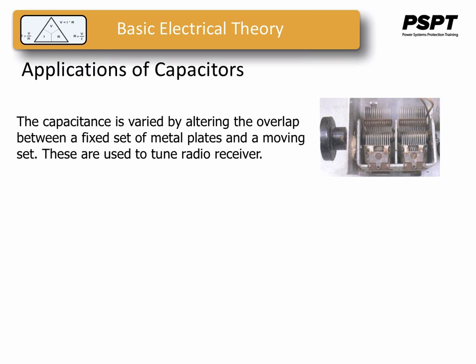They had meshing plates that varied the capacitance of the tuner, and these plates would actually move in close to each other and away from each other. So you'd vary the distance between the plates as well as the area of the plates as you turned the knob, and that would vary the capacitance in the tuned circuit, and you could tune in the various radio stations that way.